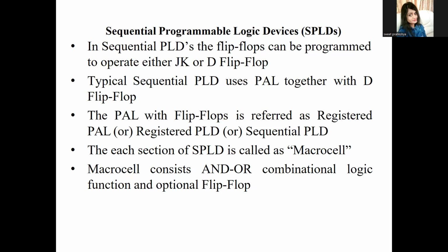As we discussed, it uses either a D flip-flop or a JK flip-flop. The inputs are fed into the D flip-flop triggered by a clock edge. As we know, when the clock pulse is one, the circuit starts working. The output then passes through a multiplexer, which is a controlling unit driven by an output enable signal. Feedback from the flip-flop can also be used as an input, allowing complex sequential behavior.